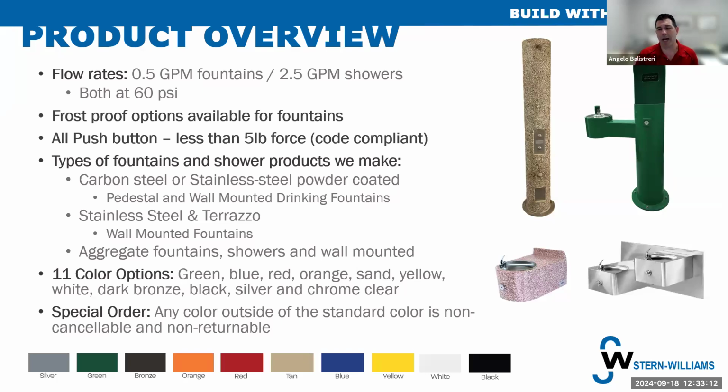I think a lot of it is more related to what's required to install one. Once you get into certain things, you have to go so far into the ground. So many maintenance, parks and rec, and service and maintenance guys would rather just say, let's mount it the way we normally would, and we know it's part of our punch list in the fall. We go around, we shut the water off, we disconnect the draw line, and everything flows out. We're protected for the winter, and then come spring, we go back and reconnect everything. But the options are there for frost-proof.